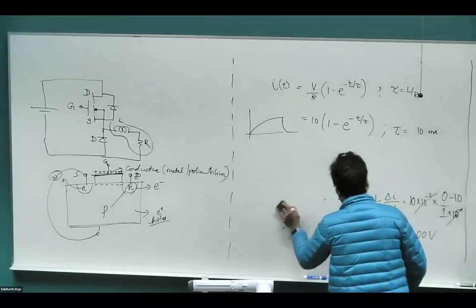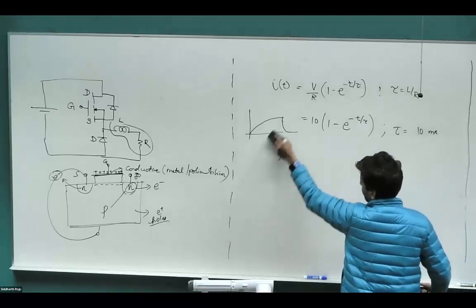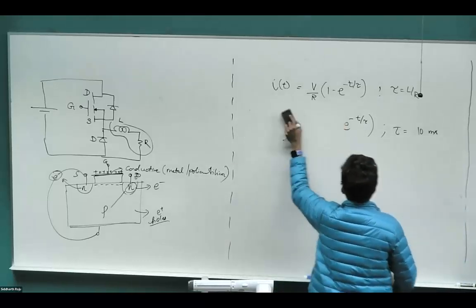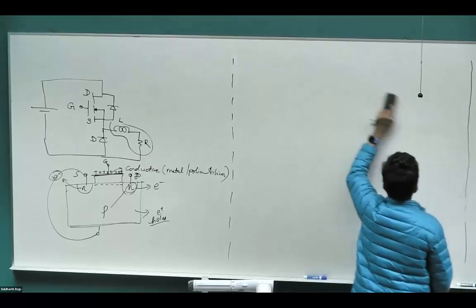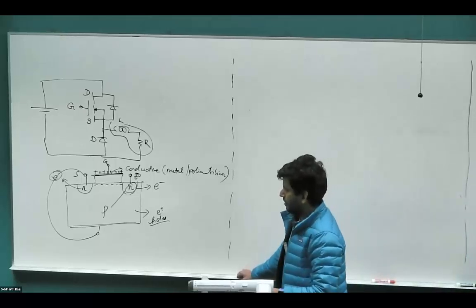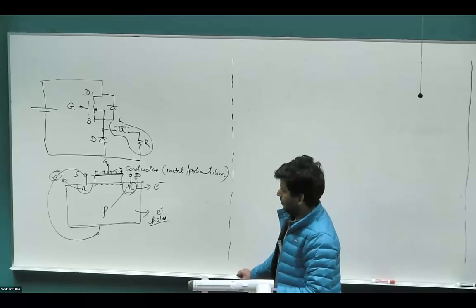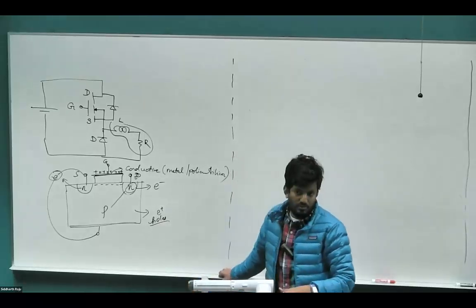So that's the very simple explanation of how a MOSFET operates. The MOSFET that I've drawn is not the structure that we use for power semiconductor MOSFETs. Those are completely different. There are drift layers and so on to allow for higher voltage and things like that, which we don't have to get into, but this is the overall simple basic idea of how it works. Anybody have any questions?